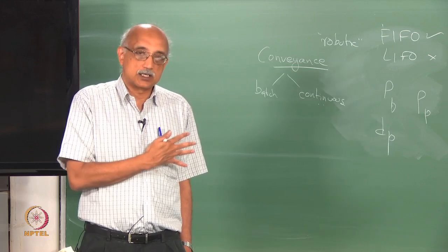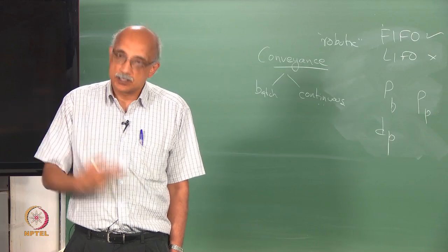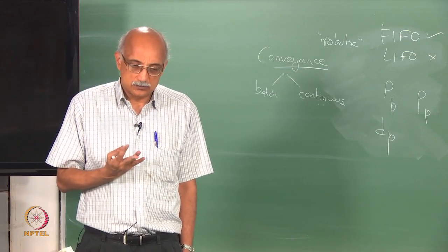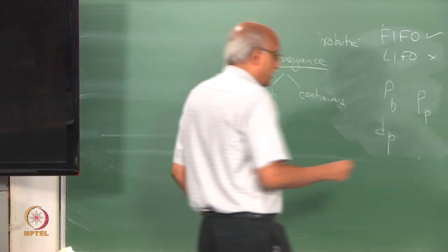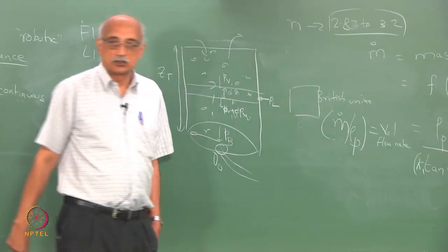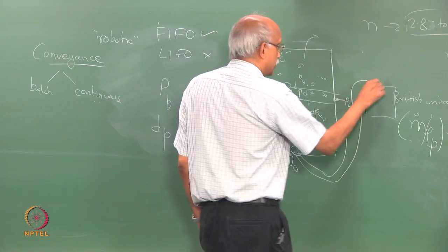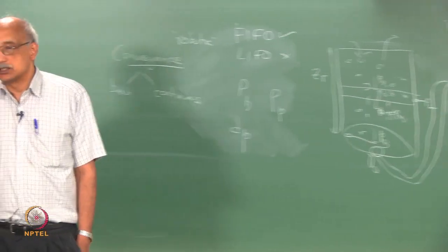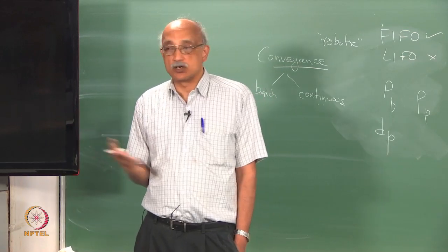If some of your processing conditions change, the nature of your particular material might change also, from being less cohesive to more cohesive and so on. So, you do not want to make the problem worse by having to, for example, take the material from here when your next process step is at some elevation over here. Now you have to pump, right, or figure out some other way of conveying the material. And if you think storage and outflow of particulate slurries is hard, pumping is even harder.